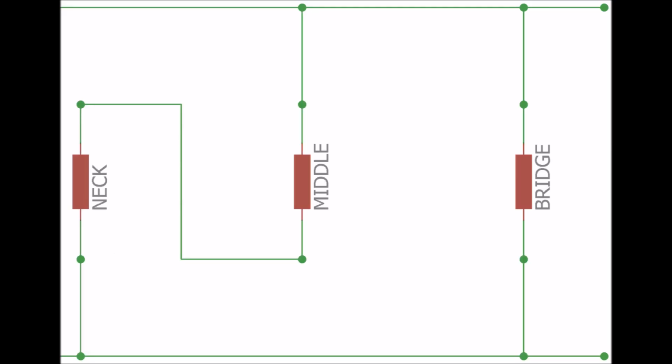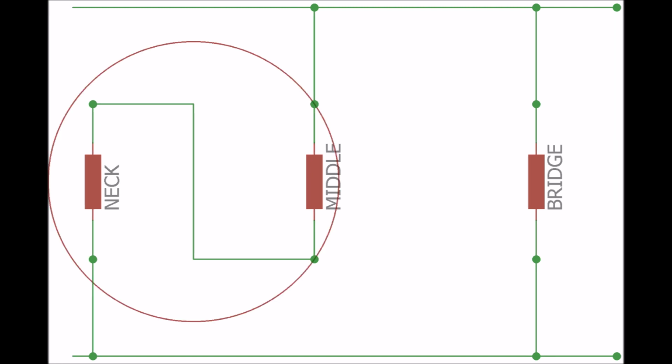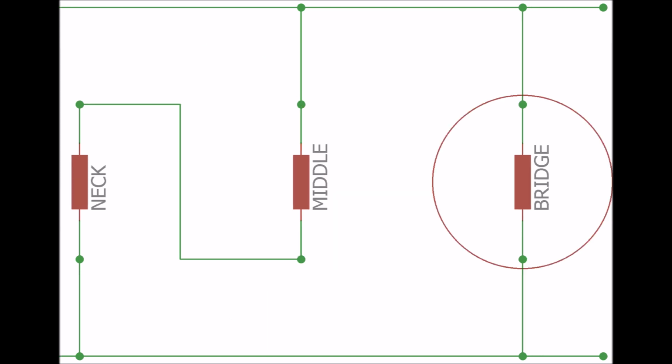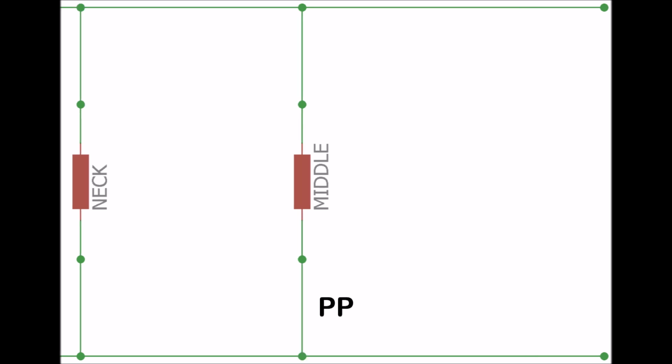The basic idea is to initially define the paths for 3 pickup combinations, and from there, the other combinations are derived. The simple combinations are merely components of the compound combinations, and they are defined in due course, as the compound combinations are defined and subsequently broken down. Take note that in breaking down to 2 pickups, there are only 2 types of 2 pickup combinations: 2 pickups in parallel and 2 pickups in series.